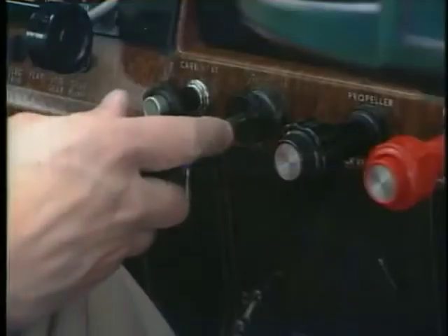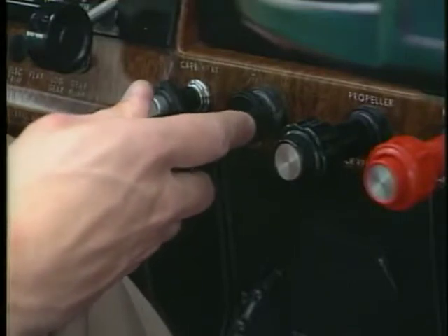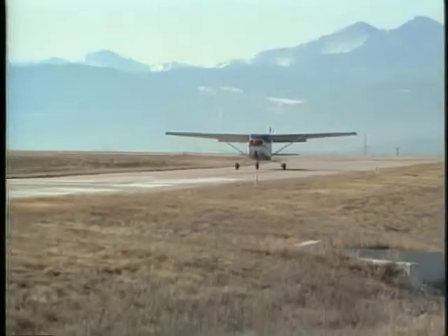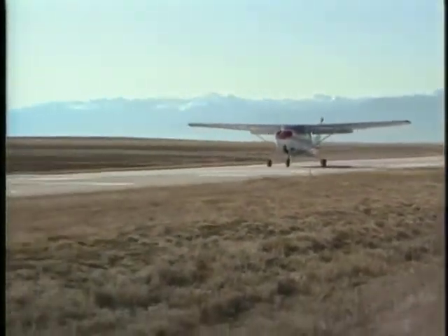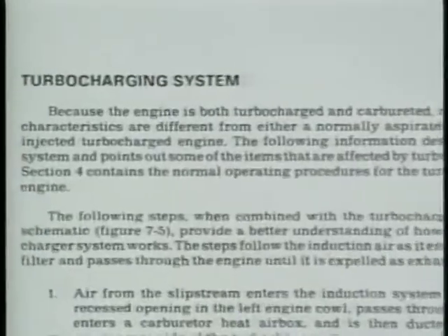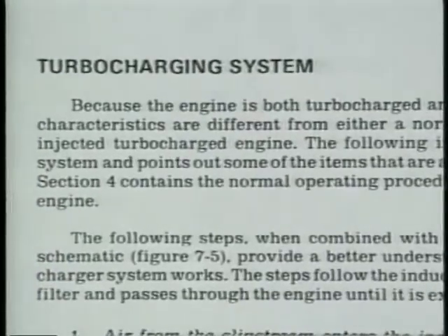When operating this type of system, you must give close attention to throttle operations, since excessive manifold pressures can be produced at low altitudes. For specific operating procedures on the turbocharging system you're using, consult the Pilot's Operating Handbook or Aircraft Flight Manual.